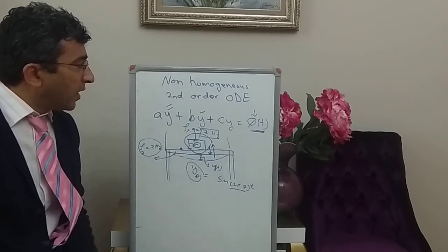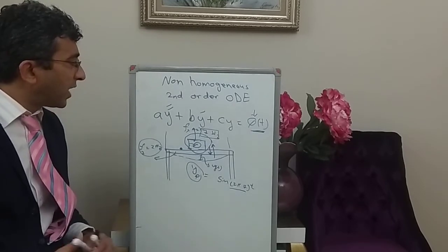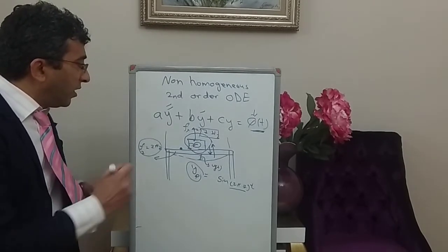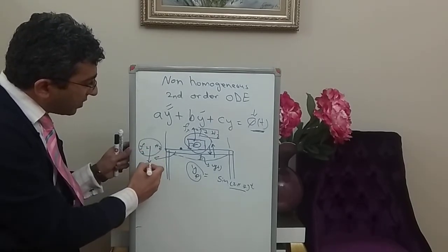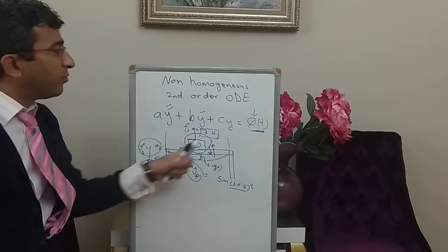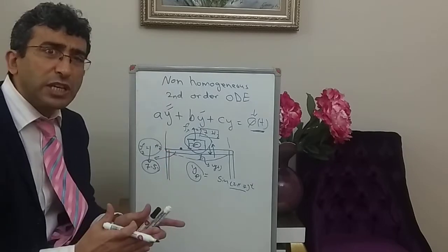Engineers should avoid a situation where the free vibration frequency of the slab is, for example, 7.5 and you apply a force at 7, because 7 and 7.5 are so close to each other.